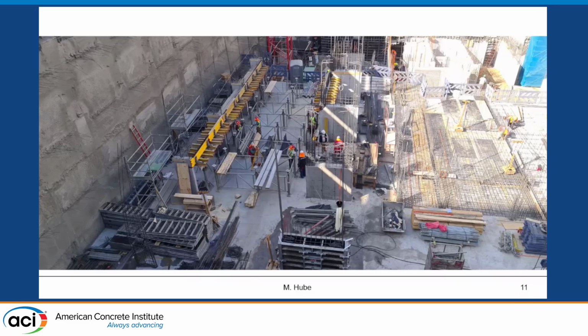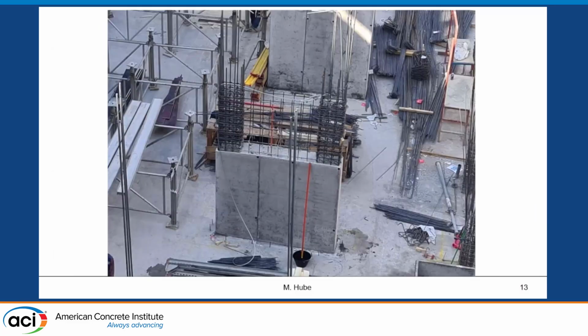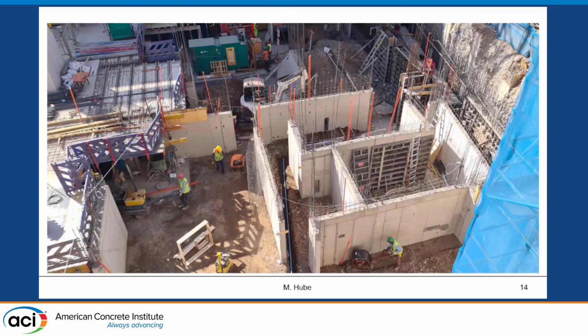So this is what the construction of a building looks like. That's the basement, and you see the walls here. There's a confinement of the wall. A big concern is what happens if you have a wall with this cross-section. How do you design this, and of course how do you do a performance-based design with an element that has this cross-section? It's really difficult to imagine if you can model this properly. Jose has made some efforts to model Chilean buildings, and it's tough because this geometry is really difficult to model. You don't know how it will behave. So that's why linear analysis works well for this.